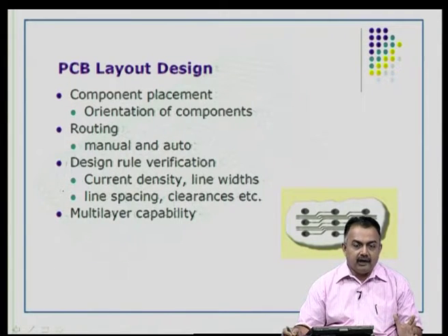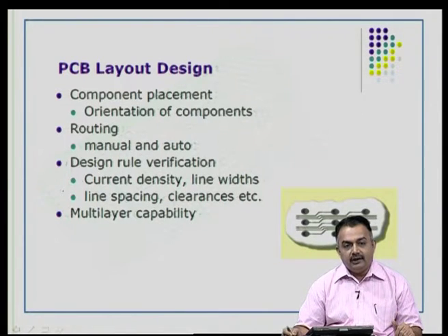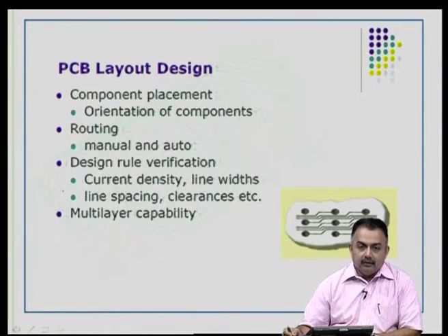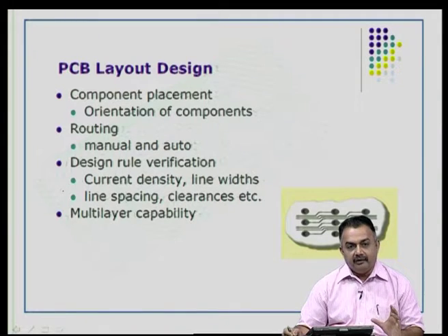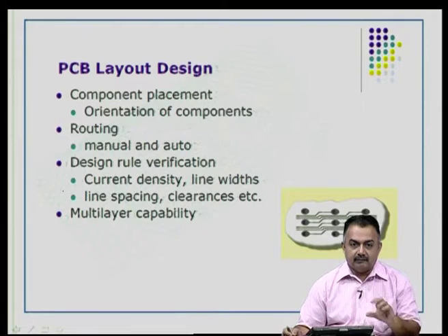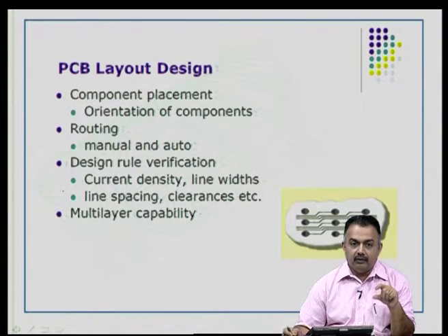Then the next module in any CADware will be PCB layout design, which means here you are working with component placement. So, in a given area which you determine as the PCB size, you have to place the entire set of components, both the actives, the passives, the electromechanical components and other parts into that given space. So, the real estate here is expensive. So, you have to make sure you utilize the CAD program to make a very good layout.